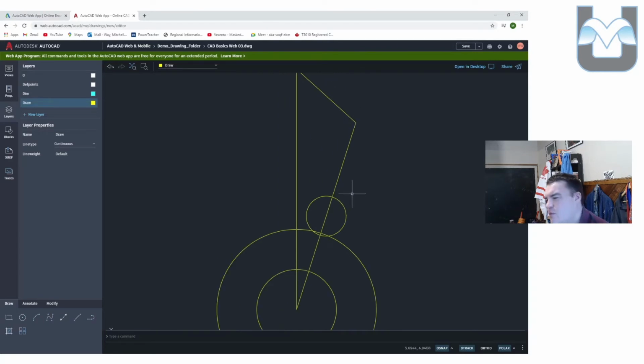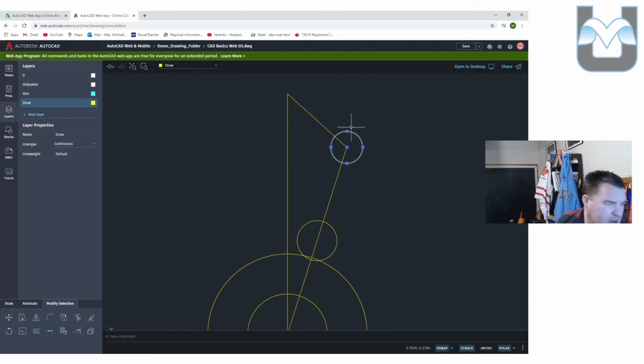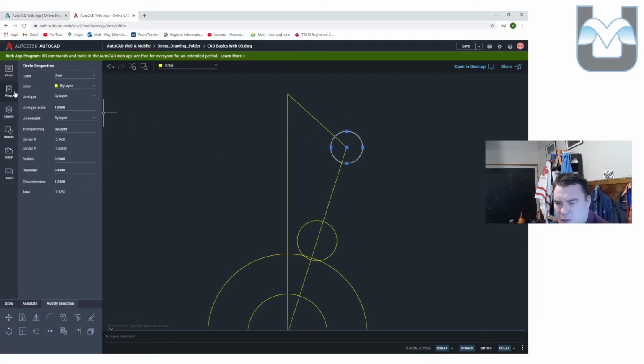And so if you trim too early, you're going to end up with things that don't quite work on this drawing. They don't quite do what they're supposed to. And don't worry, it was designed in such a way that I could see those relatively quickly. I just typed that radius in wrong. I just realized. I'm going to go to my properties and confirm. But yeah, it has a radius of 0.22 according to the drawing, which is super neat.